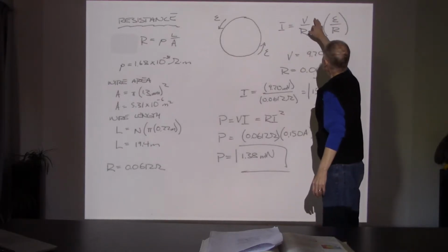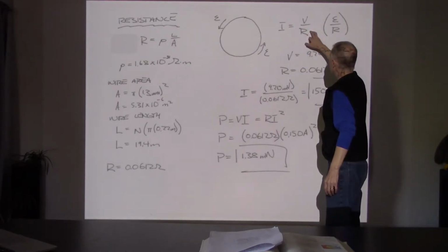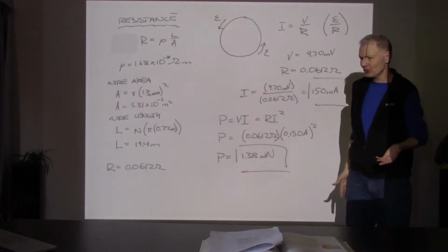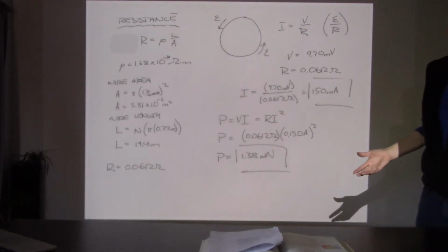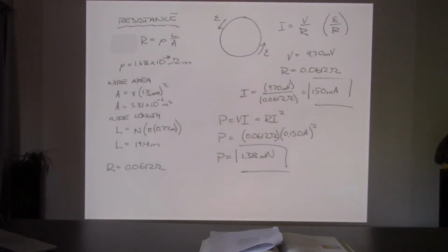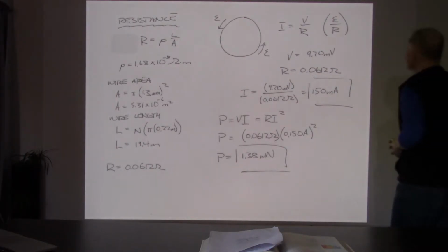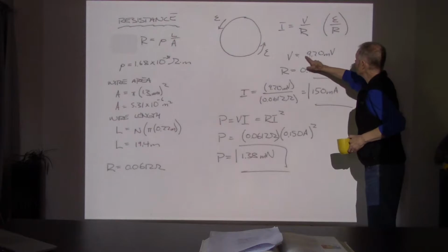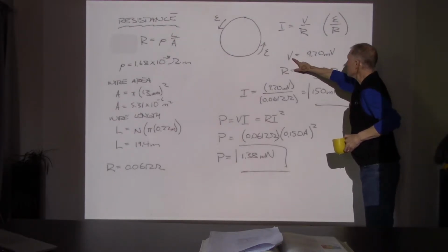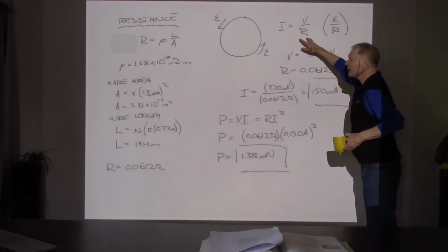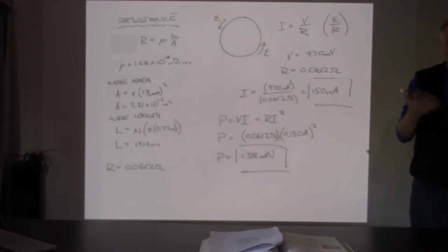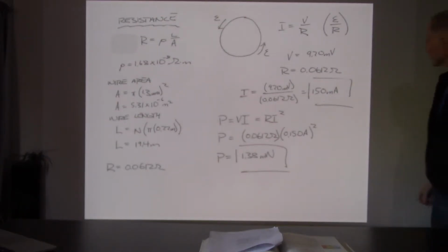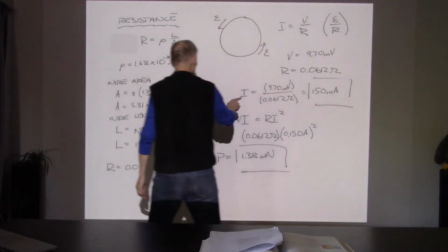The current will depend on how much voltage and how much resistance. Well, EMF is just voltage. So the voltage is whatever that EMF number was. So you can see now that this is V, driving the current. We just need to find out the resistance. Whatever the resistance is, that's going to help us determine how much current we've got.